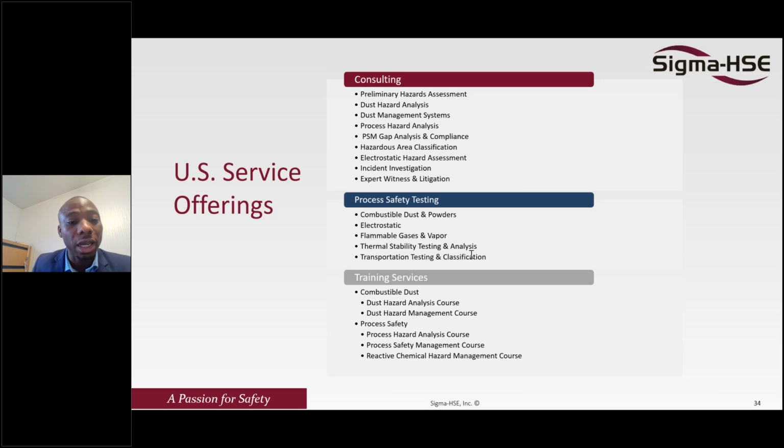What is the difference, according to you, between grounding and bonding? Bonding is when you have two metal equipment and you connect one equipment to the other, which is bonding. Connecting that equipment to the ground, to the earth, is called grounding. So those are the two differences between bonding and grounding. I can have equipment which is connected to the ground, but if I have another adjacent equipment which is not directly connected to the ground, then I use a metal wire or conductor to bridge that gap, to the same electric potential. That is bonding.